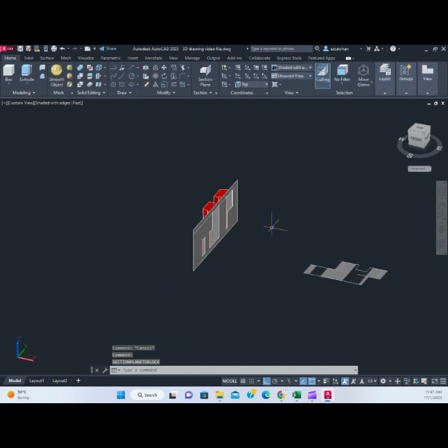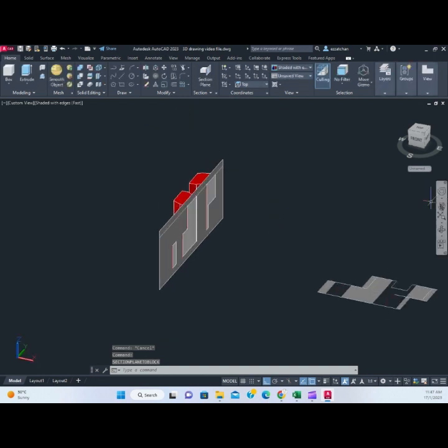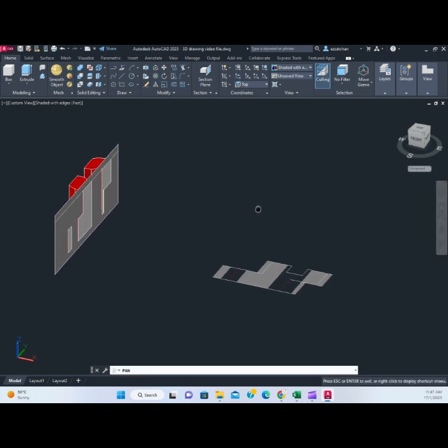Okay, so that's all that I have at the moment. As you can see, these two drawings are here. So I have the object and also the section view. If you do not like this plane here to block the object, you can always move it to a different layer and turn off that layer.